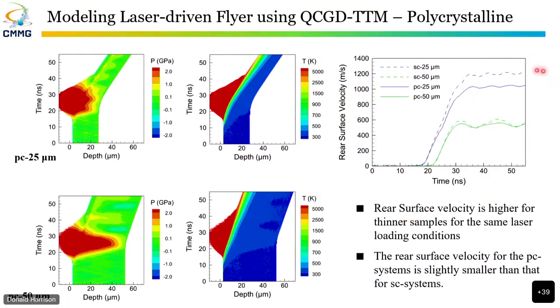So we are looking at data generated from real experiments, which will give us rear surface velocity profiles. And we want our models to say, for these velocities that you're getting, how much was the ablated volume and what are the temperatures generated, so that you start making correlations between what is happening in the material and the outcome in terms of rear surface velocity profiles.